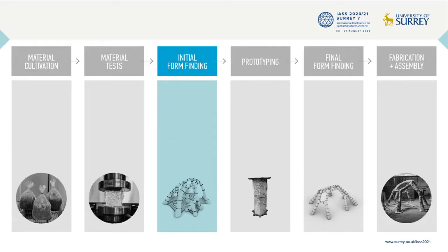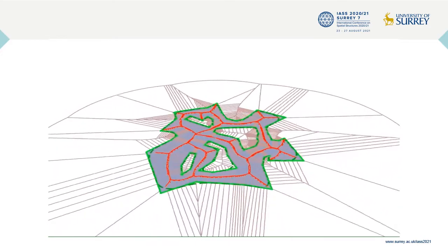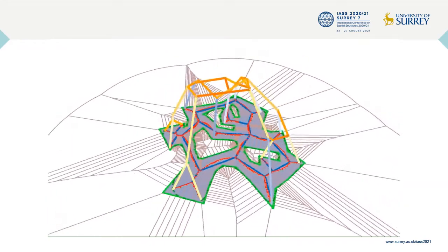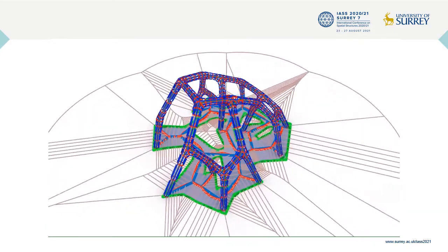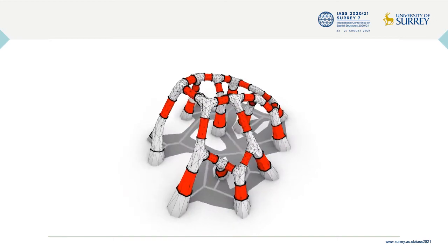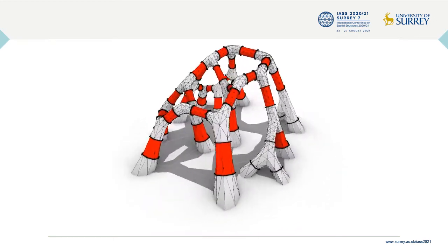Then, we explored developing a computational form finding framework for structures in which all components work under compression. We took into consideration the outcome of material exploration stage. We developed a Voronoi-based approximation of the medial axis method to generate forms that can find the horizontal and vertical equilibrium with a compressive-only manner. We discretized the form into smaller components for making it possible to be used with the mycelium-based composites.